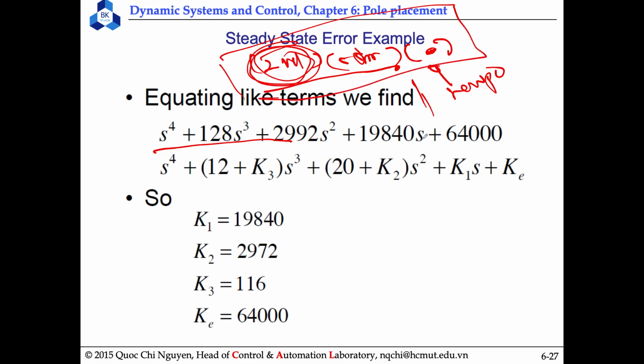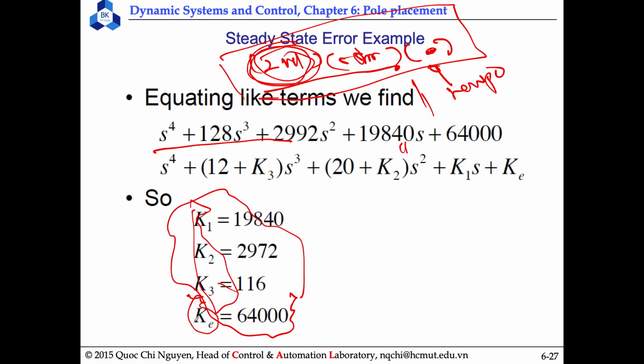We just balance the two, and we already have the new vector k and the constant Ke. Ke does not affect the steady state errors, but Ke keeps the new pole from affecting the transient response of the system already defined with the feedback control law, right?